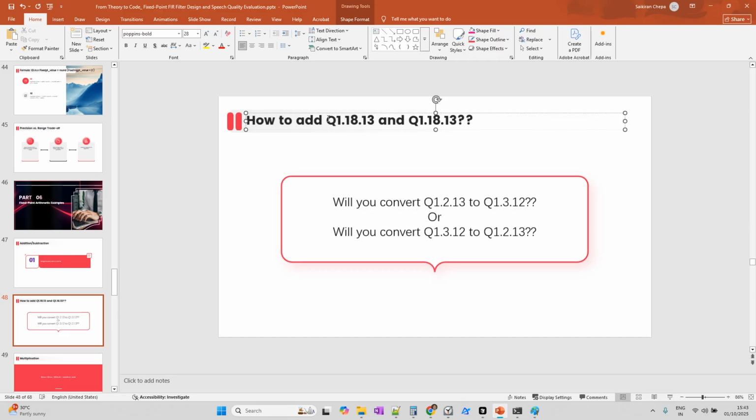So we can keep them in 30-bit. At the end we may need to convert it back to short again, with saturation. Without saturation, I think it will overflow, and negative numbers will become positive and positive numbers will become negative. So that's one problem. When you are converting it back to short, we may have to take care of the saturation, otherwise it might overflow.